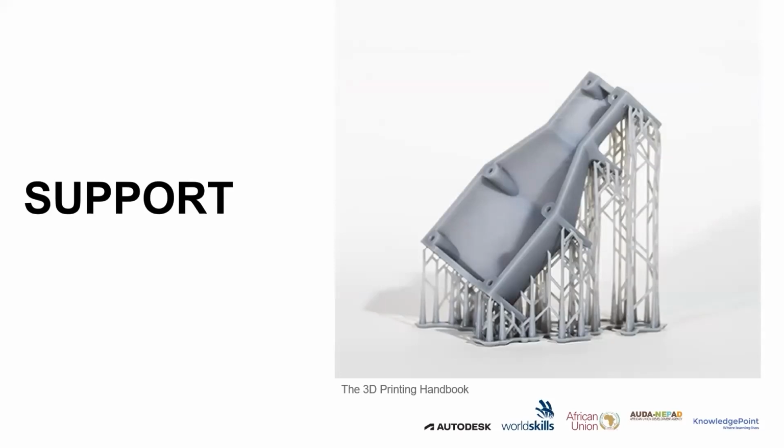Some designs might need support. It's very important for you to understand that support material really comes in handy when you have very complex shapes and complex geometry, because the printer cannot build in the air. It has to build from the floor.